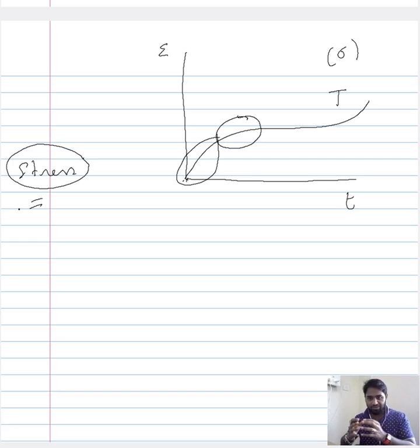However, as the time prolongs within the framework of the testing, the role of temperature becomes increasingly pronounced. What temperature does is increase the possibility of migration or propagation of the dislocations, thereby enhancing the plasticity. We saw there are different ways the temperature establishes that.